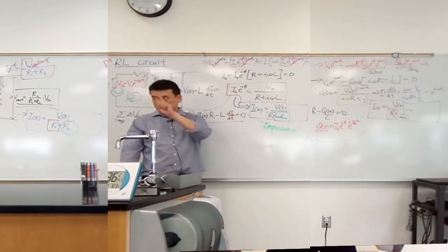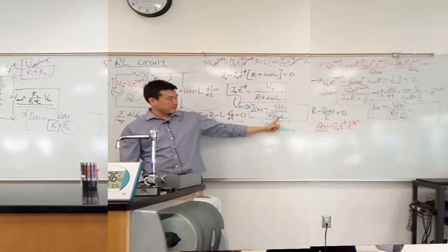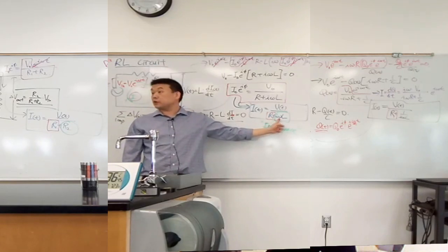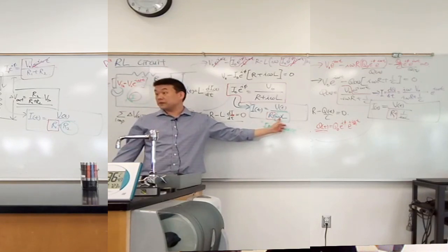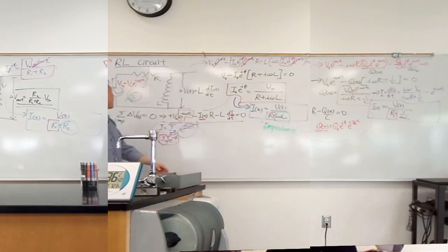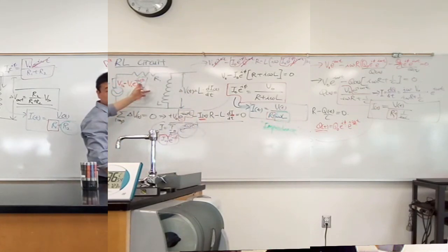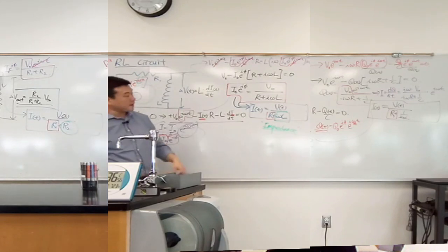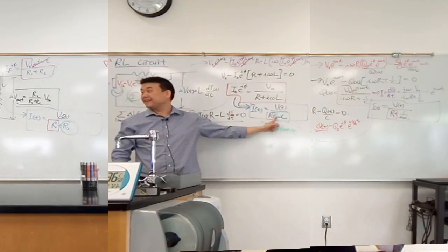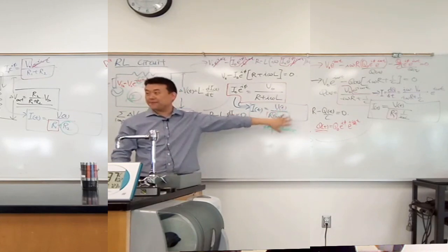It has two features in it that I want you to notice. It depends on omega, the frequency of the signal that you are applying. That's why I had to assume that my voltage is being applied at some particular frequency. And the second thing is it has an I in there, an imaginary number. So this is what we call complex impedance.